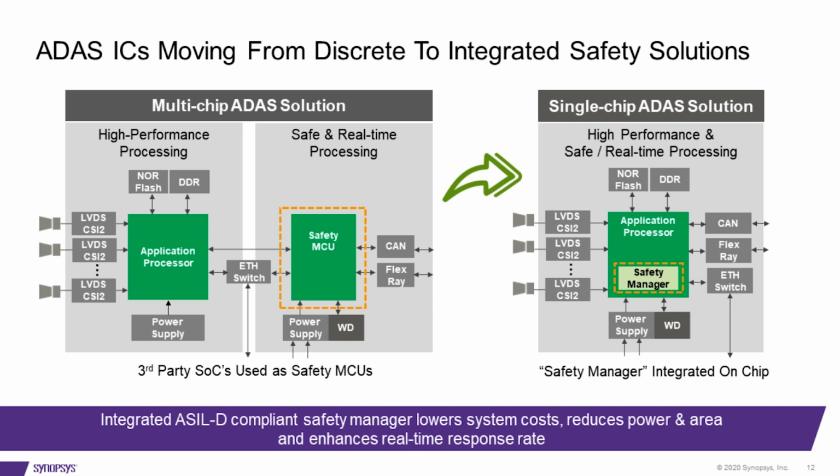Some of the traditional industry microcontroller vendors have off-the-shelf controllers that other SoC makers would then integrate on a board. So the safety SoC would effectively manage all the safety-related elements for that system, and the actual SoC vendor themselves would have less to do as far as putting safety mechanisms in the chip itself.